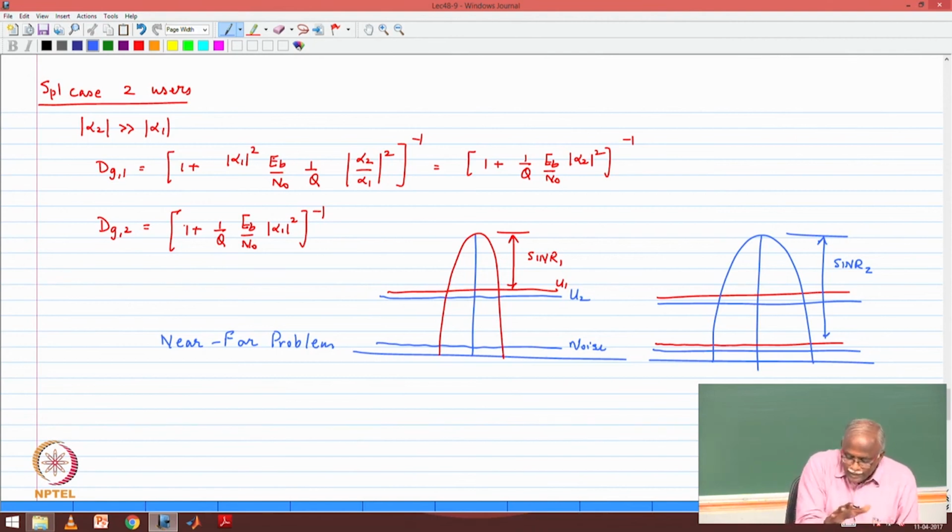It is tied to the notion or understanding of interference and power levels and spreading and despreading, all of that put together. But where does it actually creep in? When all of them are under ideal power control, it does not show up. But when one of the users does not obey power control, then it starts to affect all of the others except the one user who is not obeying power control. Okay? This is probably one of the most important questions that you will need to answer.